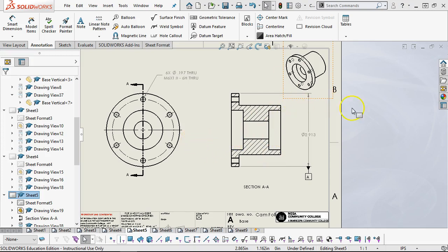All right, so positional on the M6s. We have a standard tolerance on the OD. I think I intended for this to sit on that through bore in the vertical. So it's going to be your choice of, do you control this outside diameter fitting into the spot face on the vertical, or do you control this second step and have it be the slip fit, giving it a positional location, but also taking some of the load and transferring it from the housing into the vertical. All right, we'll come back to this one.